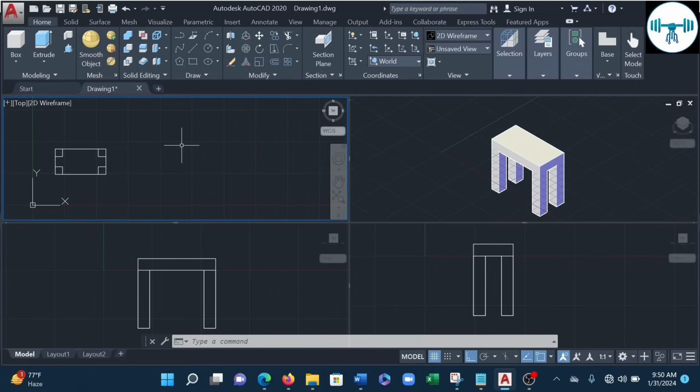Okay, we are going to draw a funnel using loft. When we want to draw a loft, we draw concentric circles with different diameters, and then we arrange them at their various heights, and then we perform the loft. We can perform the loft either in ascending order or in descending order, but it has to follow a pattern. Now let's go straight to action.